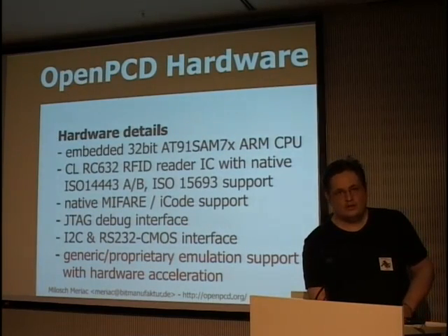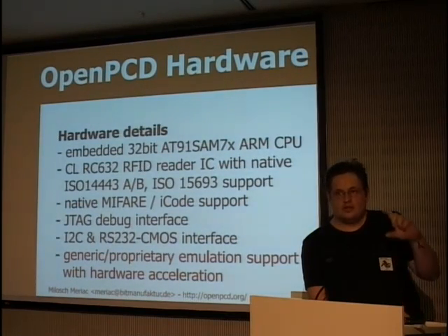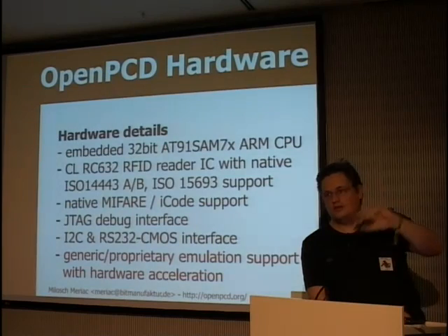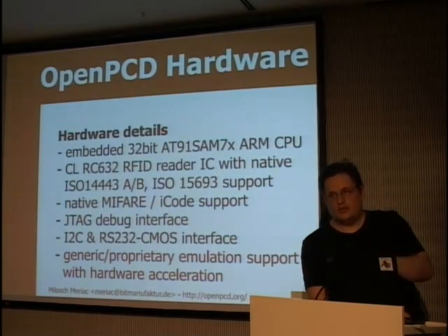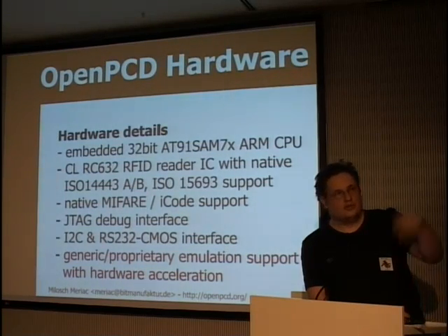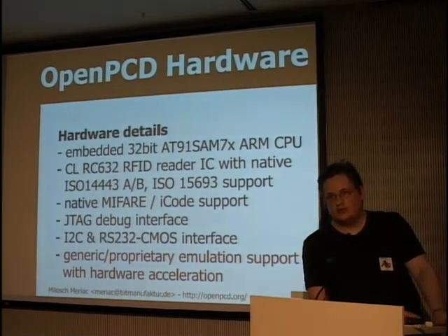What we also wanted to achieve: we intentionally chose a relatively big microcontroller. We don't use that much flash for the common read applications, but the basic idea is that you can store the complete RFID protocol code inside the reader. This means that you can attach, for example, the reader to a door, and you can use one of the I/O pins we provide or the serial interfaces to, for example, trigger door contacts and stuff like this. You don't need a PC to solve this. So we try to provide you reasonable interfaces.